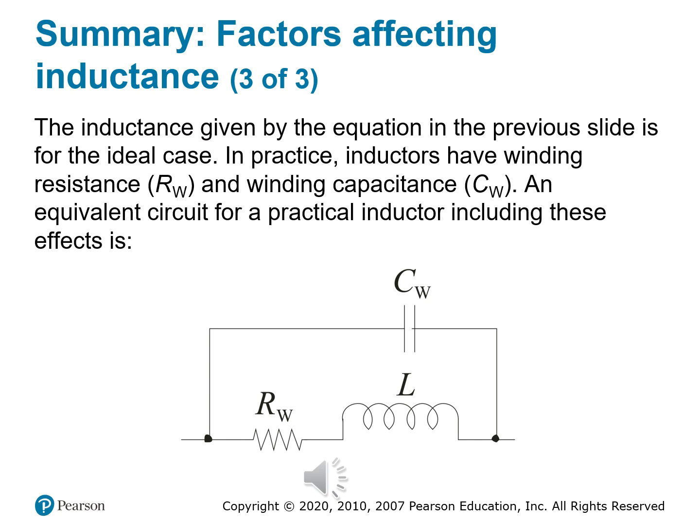And here's the truth, no inductor is perfect. Every coil of wire has winding resistance, R sub W, because copper isn't a superconductor. It has winding capacitance, C sub W, from the electric fields between the coil turns. And these imperfections show up especially at high frequencies, where parasitic effects can shift your entire circuit's behavior.